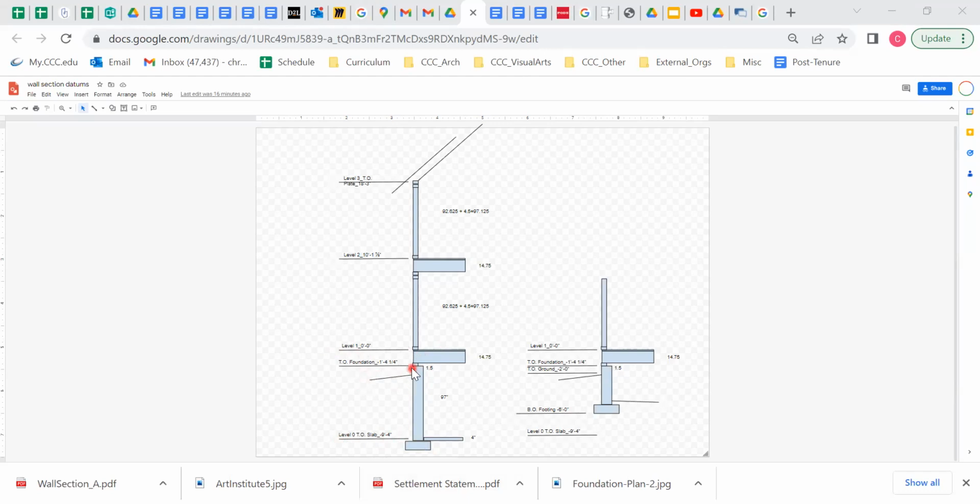Generally speaking, you want that to be below the foundation wall to keep water from penetrating. We'll get into those details a little bit later, though. But basically, this allows for a full height basement. So some of these dimensions that you see here are thinking through all the dimensional requirements that we would need. And we have a 4-inch slab at the bottom that just sits right on top of that footing.